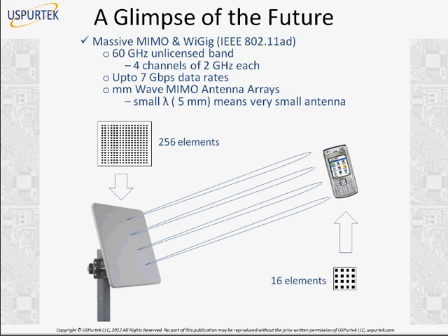With this, what you get not only on the handset side but on the base station side, you see in this typical example you are having 256 elements within the size of a pizza box. I think all of you must have seen a pizza box. What is the size? It's a handheld size. Within that size you have 256 antenna elements with this high frequency. So this approach collectively we call massive MIMO. It's a very intensive research area at this time, but definitely we are going to get some commercial applications of this in the coming years. Using massive MIMO, we will have MIMO implemented almost everywhere.